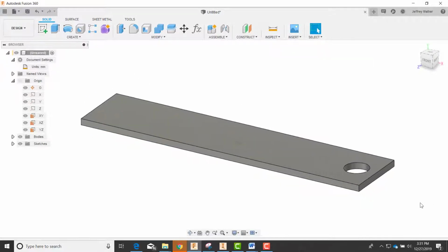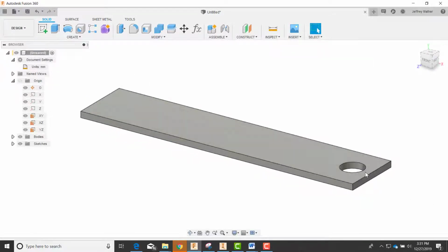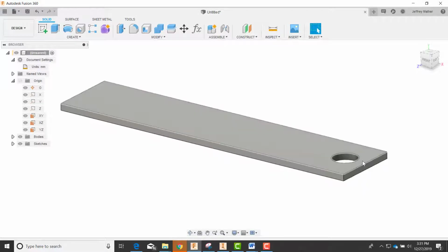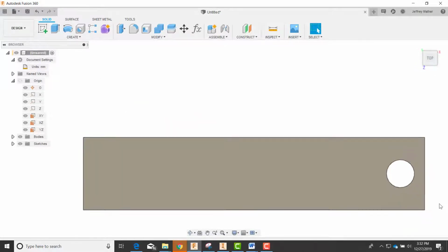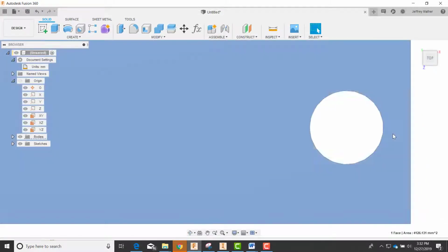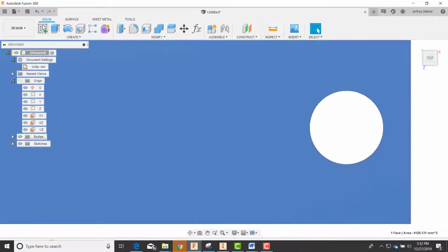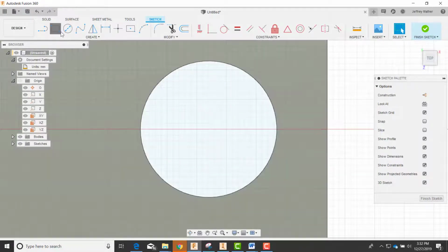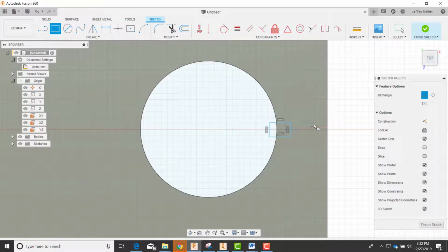Alright, so we're going to put a load suspended over here, and remember that was on an eye bolt, and so I want to identify the location where that load will be placed. And so I'm going to do a little trick here that's commonly used in FEA analysis. I'm going to start a new sketch on this face, and I'm going to then draw a rectangle about like that, and I'm going to draw a second rectangle over here about like that.